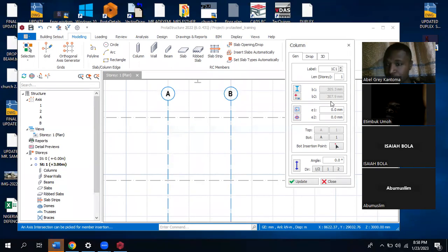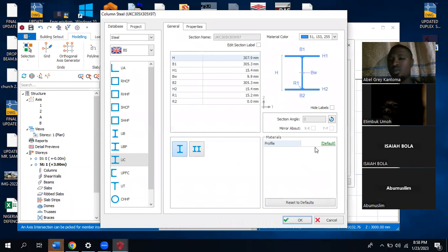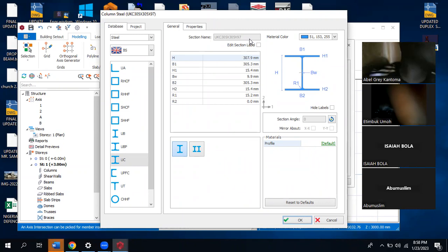This is the column property. So if I click now here, your design is actually based on trial and error. So you pick a section, analyze, and design. When it fails, you actually increase the steel section. Okay, so as an engineer, when you are designing, thank God we are all engineers on the platform, we design based on safety and also economical.